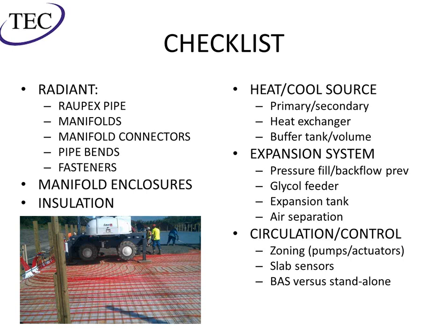Slab sensors or snow moisture sensors. You always want to be cognizant of if you need those. In indoor systems, depending on the flooring type that's going over it, usually determines if you want a slab sensor. If you're just doing a garage or an extra basement area, slab sensors with a concrete slab aren't as important. If you're doing a wood floor that's sensitive to temperature, you definitely want to be including slab sensors.